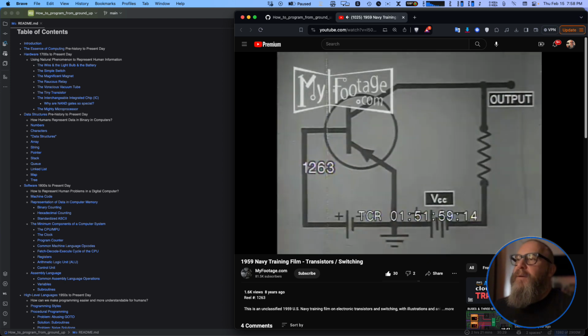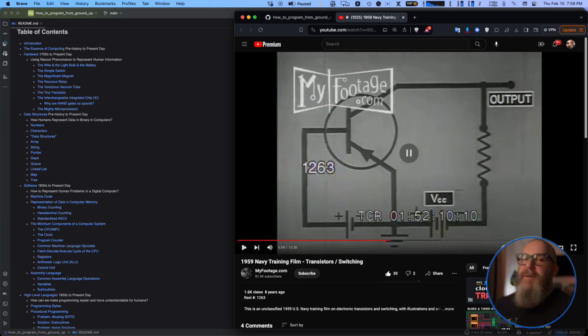When the switch is off, there's reverse bias on the emitter junction. And without forward emitter current, no current can flow through the collector. So because you don't have to heat an element here like in the tube, that's a big reason why transistors are way more energy efficient.